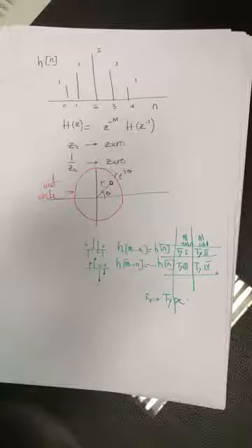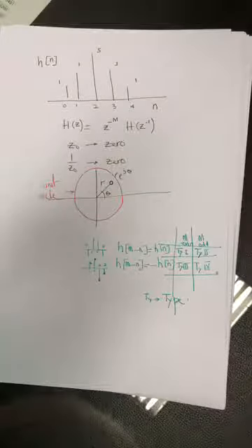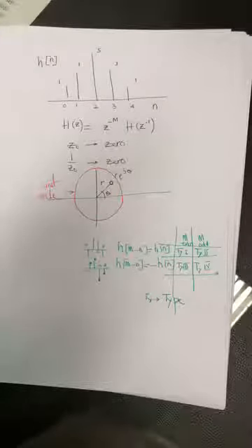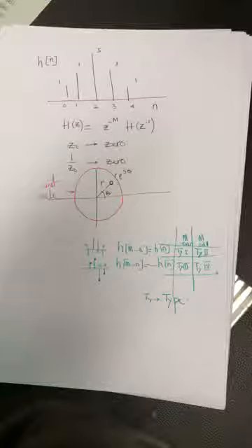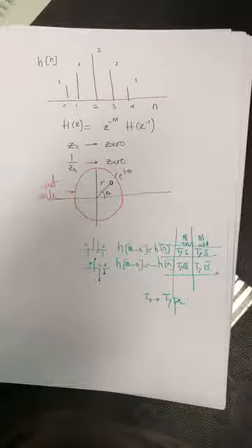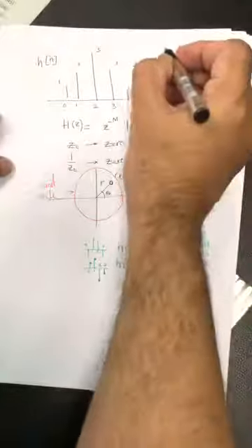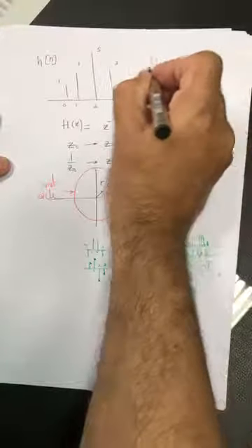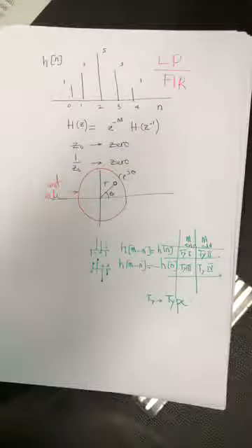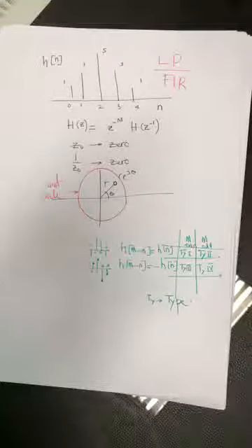So, I want to first recap what we did last time. Last time we started studying linear phase FIR filters. IIR filters have this problem of non-constant group delay, meaning their phase is not linear. So we want to make sure that the filter we design has a constant group delay.